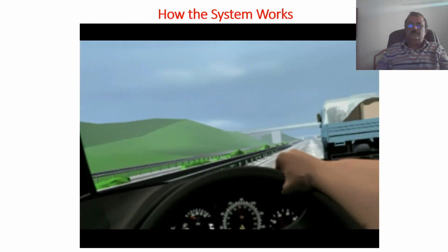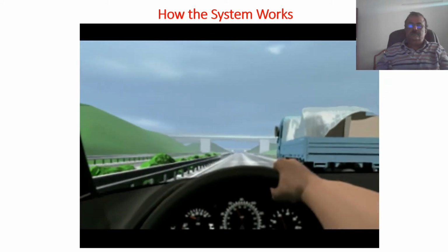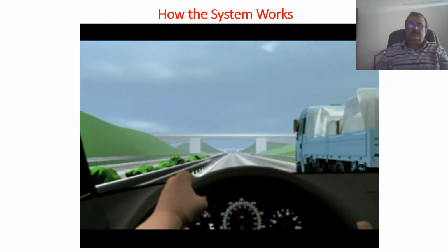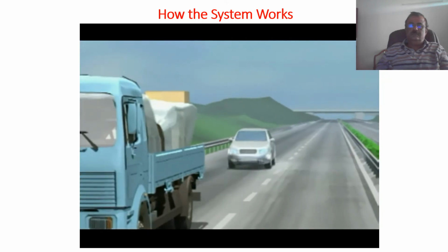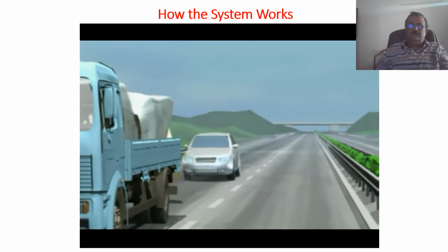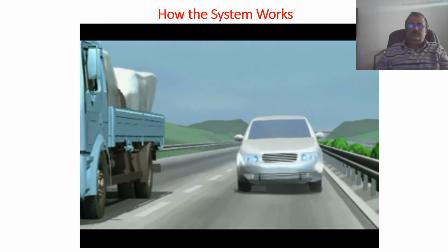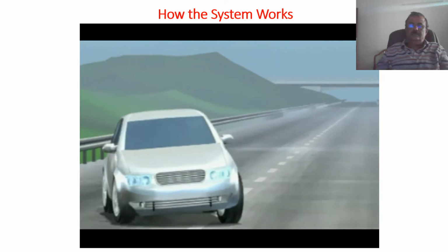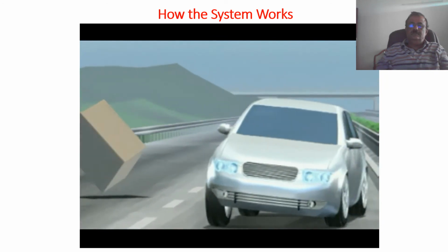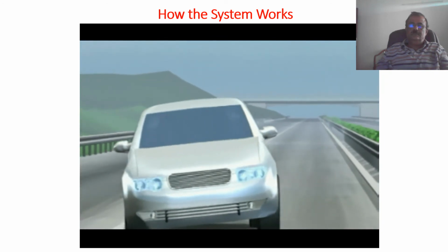In everyday driving, it's normal for transverse forces to arise. But when you drive a bit too fast or turn the steering wheel, these forces can negatively affect road holding. But the Electronic Stability Program, ESP, nips that in the bud by controlling the brakes, if necessary the engine, and if need be the transmission as well.